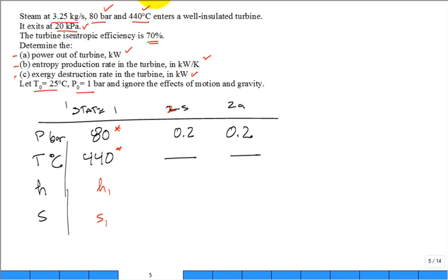So what we do is we jump back and forth so that you've done this. This is all just thermo 1. So this value gives us S2. Knowing S2 and P2, we can get H2, and we'll call that H2S, assuming isentropic expansion from 1. We then calculate the work of the turbine isentropic, H1 minus H2S. You want to find the work actual.